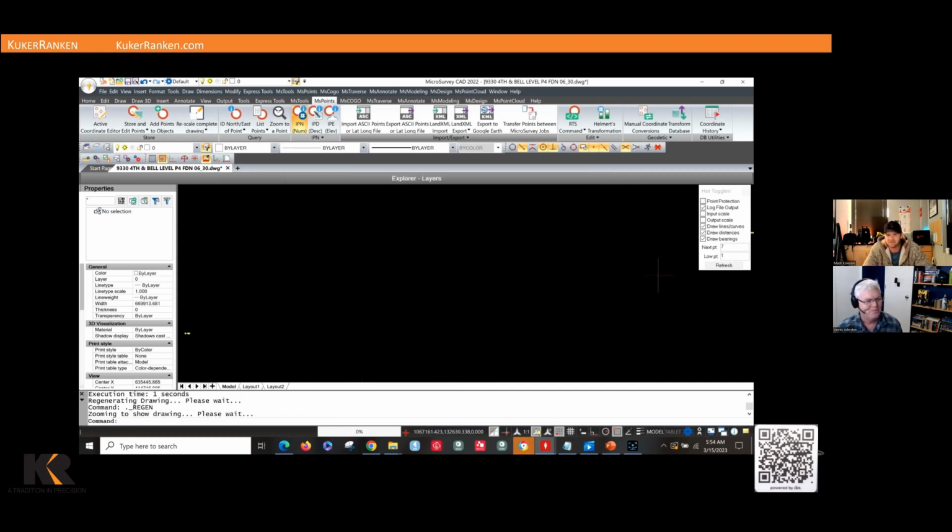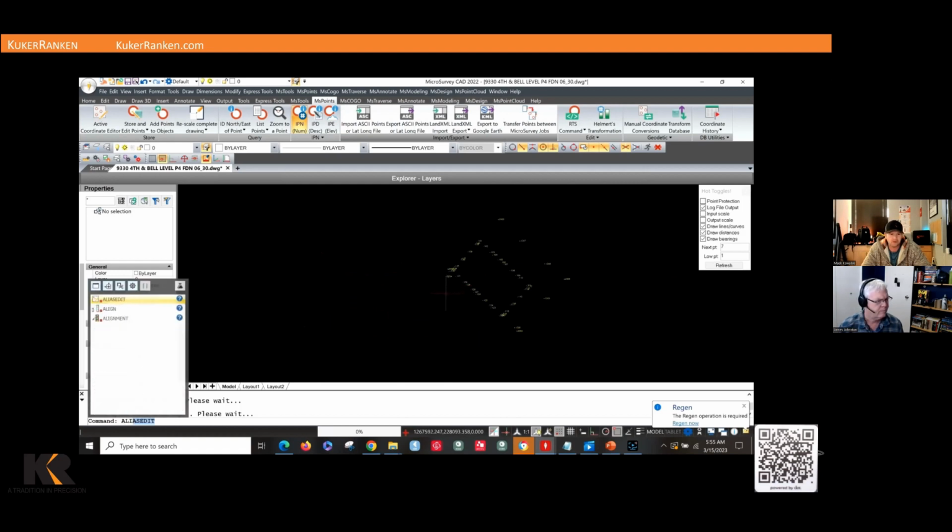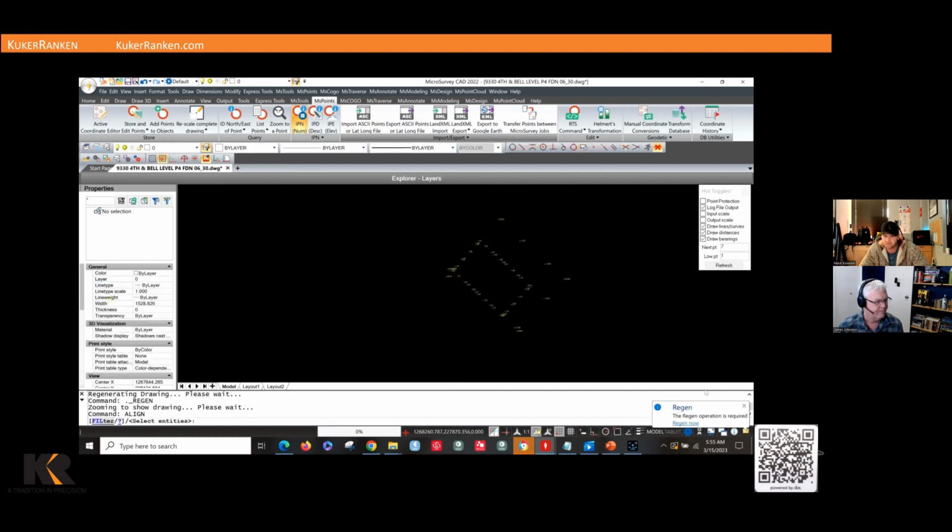So right now we have our points on our state plane, and then we have our drawing on my user coordinate system, which is the 1,000, 3,000, I believe. You're going to zoom in. We'll select a line, and apparently it already cut. There we go. So I just typed it into the search bar, just like any other CAD program.